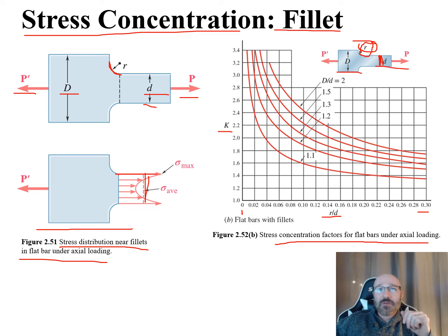So between our ratio of our head size and thickness here, our big D over little d, we can start out with 2 all the way down to 1.1, and how does that affect it? This is something great to reference back to figure out how we minimize, or how we get the desired stress concentration factor right here when we're setting up our specimens.